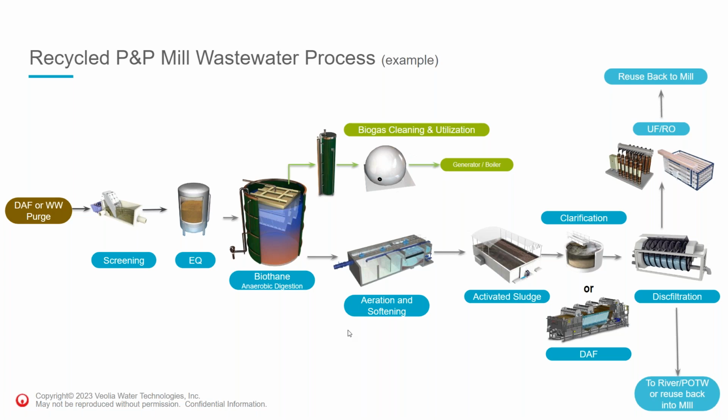Softening. Veolia's patented technologies are used to remove hardness from the effluent to enable biological treatment and subsequent water reuse. Flotation, clarification, and filtration. Veolia has several technologies for solids removal, whether it be solids flotation after an MBBR system, clarification of a high concentrated mixed liquor activated sludge stream, or final effluent polishing. Our technologies include Poseidon DAFs and Hydrotech disc filters.